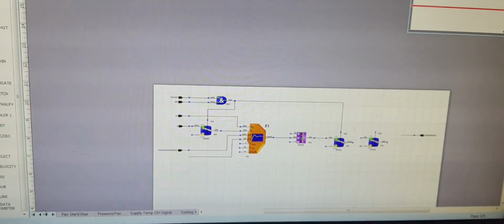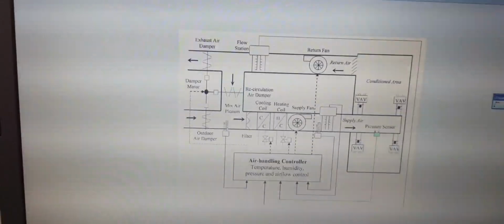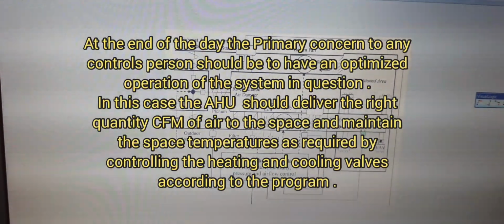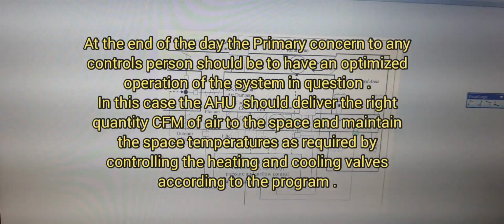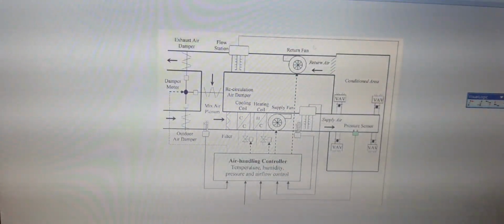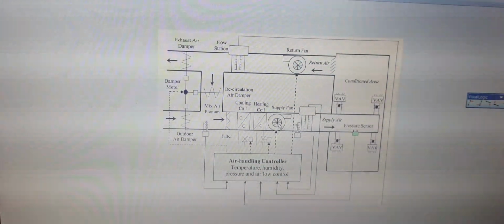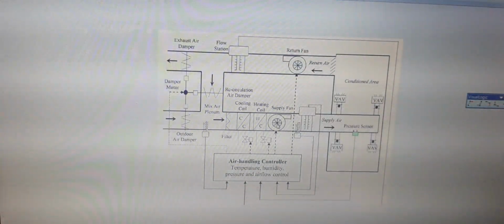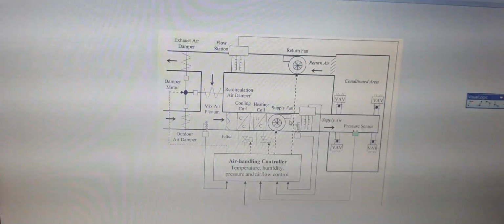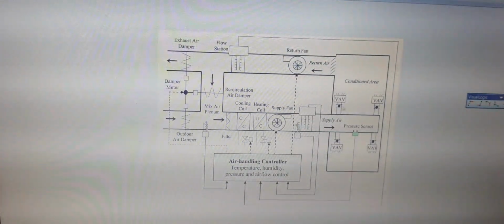We have, as you can see, we make sure that the air handling unit is discharging the right set points. There's no issues with the fan. So as I mentioned, the alarm condition of the fan, we make sure there's no issues with the fan. The fan is running. We have the status. We don't have any high pressure issues, and we have the right amount of set point maintained. There's no compromise in the VAV and the duct system.